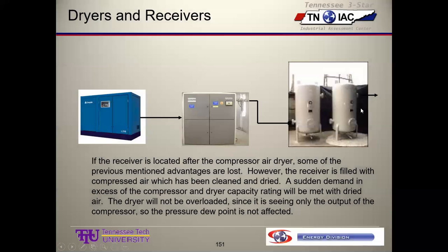I should have another slide that shows the storage tanks in both locations. So it's a good idea to have wet storage to help your dryers. It's also a good idea to have dry storage to be able to supply compressed air spikes with dry air downstream. More storage is always good. Storage never hurts you in a system. It's just the fact that you have to pay for it on the front end. But once you have it, you should have it for a long time, because there's really no moving parts associated with it.